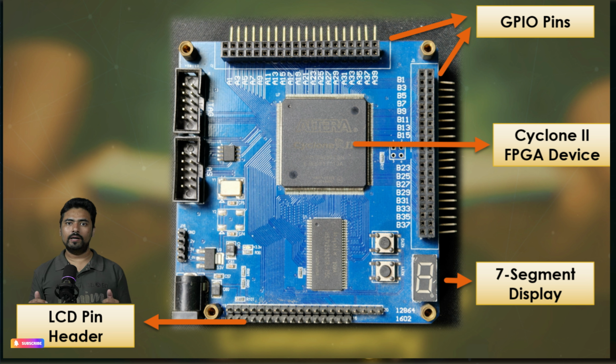Lastly, we will develop a communication module, a UART, Universal Asynchronous Receiver Transmitter module. This module will work alongside the state machine and enable communication between the FPGA development board and a computer over the RS-232 interface.